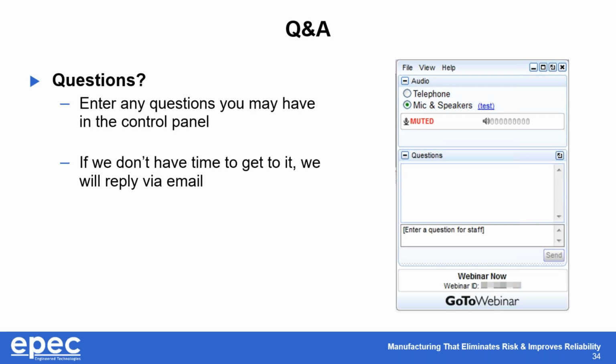Second question, and again, this is a fairly common one, is can a shielding film or silver ink be used for current carrying requirements? The most common being a ground return circuit. Per the materials manufacturer's specifications, the answer is no, it should not be used as a ground return.